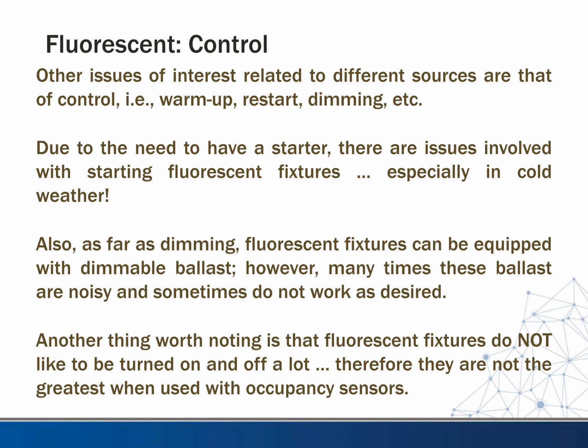The final thing worth noting is that fluorescent fixtures do not like to be turned on an awful lot. Therefore, they're not the greatest choice when using occupancy sensors, especially when you're going to have a lot of turn on and off, like in an office or something like that. You have to be careful.